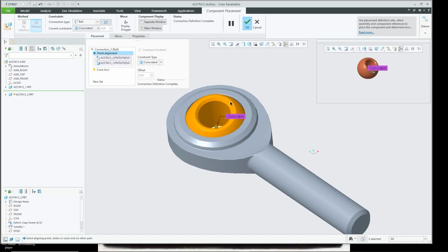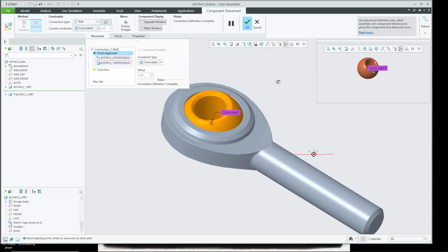So I'm not using a dragger associated with it, just Control Alt and the middle mouse button will only move the part that you're assembling. If I just use the middle button, it does the whole thing. Now, I do that because what we are able to see is that this thing has full freedom while it's in here. That's not what we want. We actually want to be able to go in and control that.